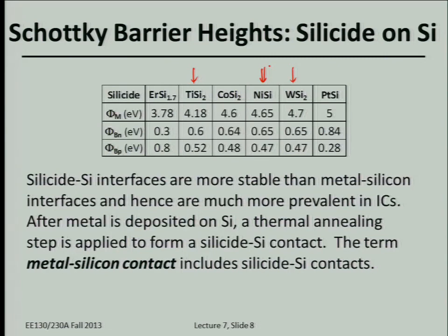So that's like 10 to the minus 1 centimeters. And what's the typical resistivity of very heavily doped silicon? A very, very heavily doped silicon is maybe on the order of 1 milliohm centimeter. So let's say you want a millimeter long interconnect, and the cross-sectional area is 1 square micron, 10 to the minus 8 square centimeters. Basically that's 10 to the 7, so 10,000 ohms for the interconnect.